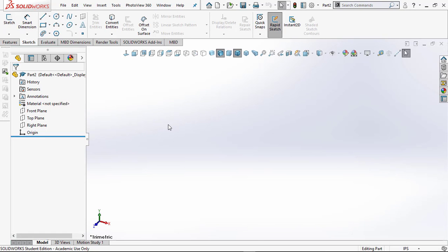Now one important thing to note about SolidWorks. In the world of 3D, there's different kinds of three-dimensional modelers. There's ones called NURBS. It's a NURBS modeler. It stands for Non-Uniform Rational B-Splines. A product like IronCAD is an example of a NURBS-based modeler. And then you have what's called primitive-based modelers. A primitive-based modeler is where you create toruses, cubes, spheres, cones, and you draw from there. SolidWorks doesn't work that way. SolidWorks always works from a sketch as your starting point, and then you create whatever you want to create.